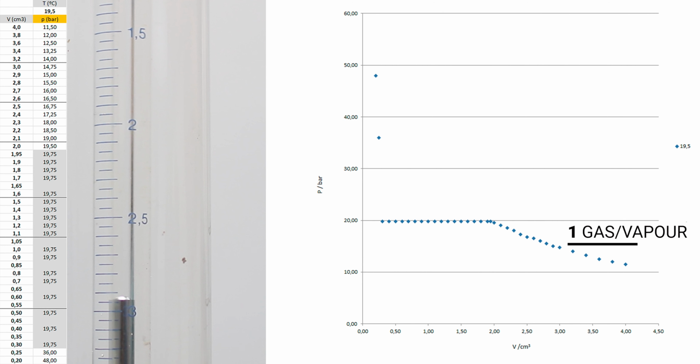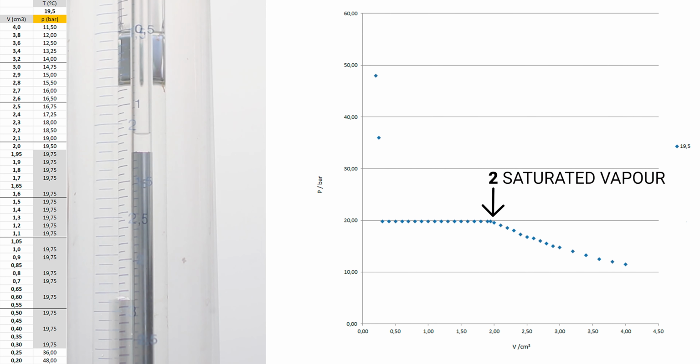The gas region, in which the fluid suffers a smooth increase in pressure as the volume is reduced at constant temperature. This region is called the superheated vapor region. The appearance of the first drop of condensed liquid. We can state that the gas, at this pressure and temperature, has saturated its capacity of maintaining all its molecules in gas state, grouping because of this some molecules in the first liquid drop. We denote this state as saturated vapor or saturated gas state.